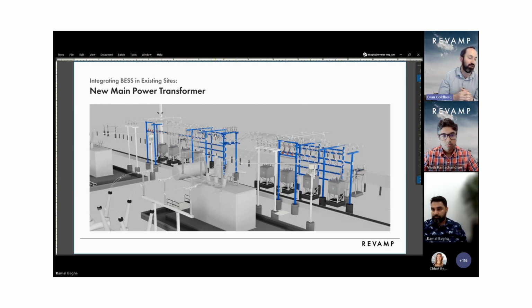And what that can mean is, if you're prepared for it, if you ever have to take one transformer out of service, you can close in that disconnect. And now, instead of losing the production of one transformer, you can utilize the other transformer to push that power out to the POI still, right? So planning ahead, thinking through some of the ways that you may want to interface this new BESS into your existing substation can pay dividends in other ways. Next slide.